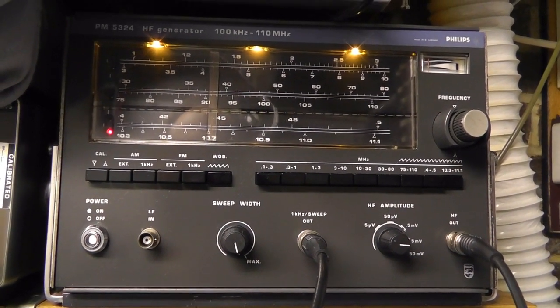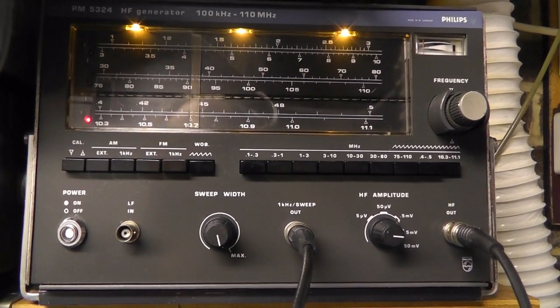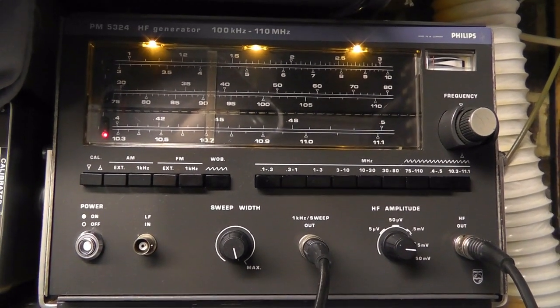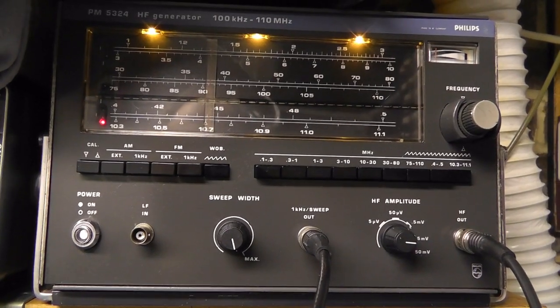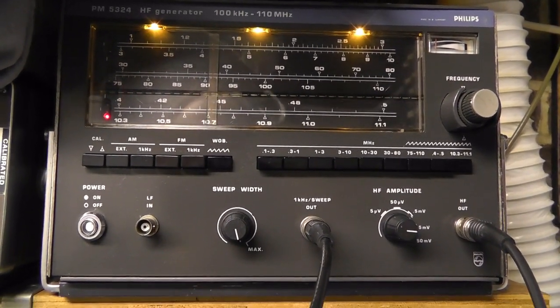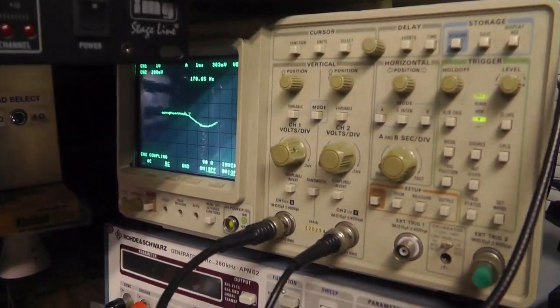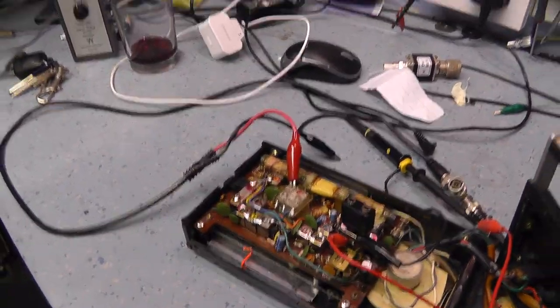You've got to remember this is a sweep generator, and basically the Wobbulator sweeps around a centre frequency. As you can see on this display at the bottom here, we're centered at 10.7 megahertz and we're sweeping either side of 10.7 megahertz. Now, connection wise, which I know he was interested in, the sweep output, not the RF output, the swept output goes to the X input of the oscilloscope. The RF output goes to the input of the IF amplifier, and I'll show you which connections I'm making on this radio in a moment.